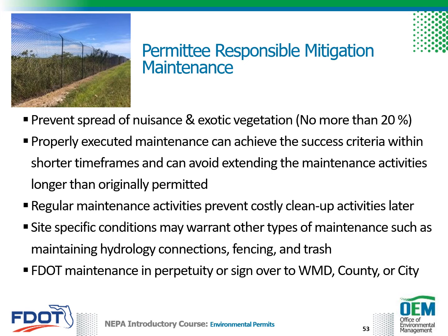Properly executed maintenance events may help the mitigation site achieve the success criteria within shorter timeframes and can avoid the need to extend the maintenance for longer than originally permitted. Site-specific conditions may warrant other types of maintenance, such as maintaining hydrology connections, fencing, and trash. FDOT maintenance is required in perpetuity unless agreements are in place with the water management district, county, or city.